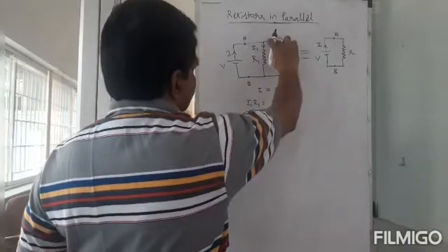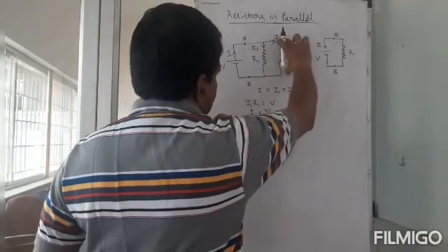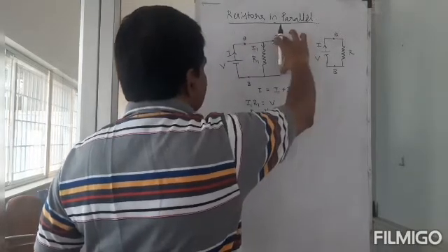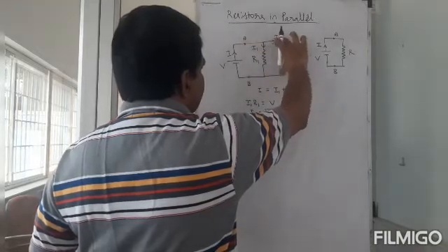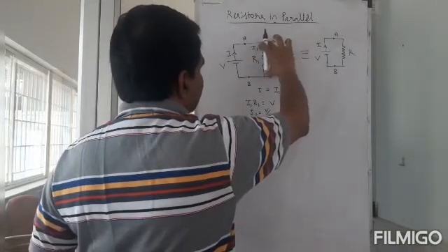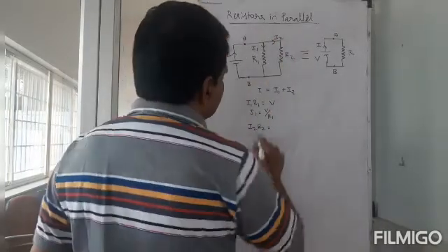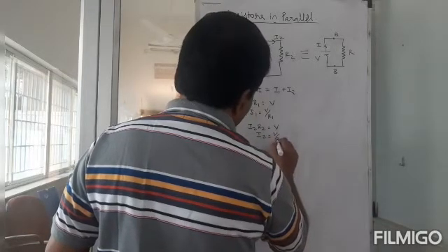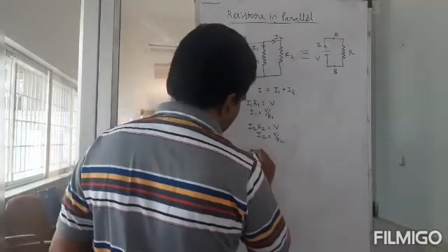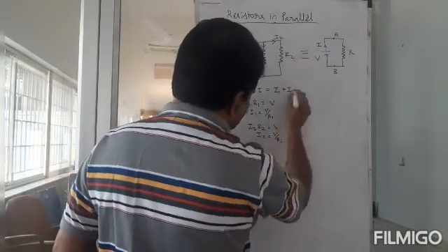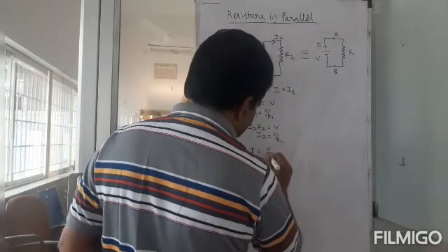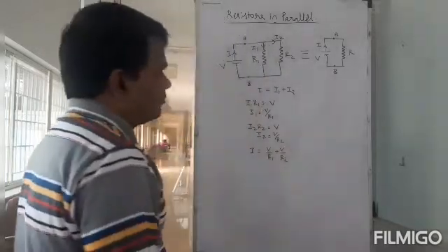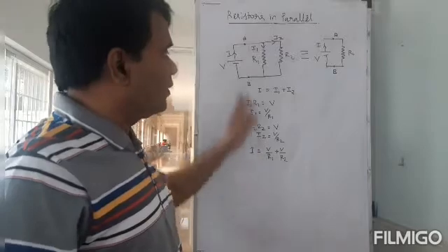And then we do the same thing for I2. Okay. What's the voltage across this resistor R2? That is I2 into R2. And that should also be equal to V. You see, you're connecting it to the same 2 points A and B. There is nothing in between, just wire. Okay. So this is also equal to V. So here I2 is equal to V by R2. And what is I here? I here is equal to I1 plus I2, which is equal to V by R1 from here plus V by R2 from there. Okay. Now what did I say here?